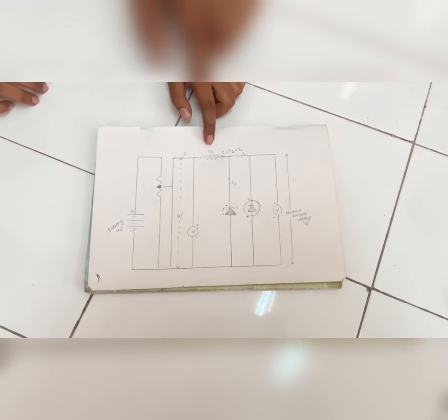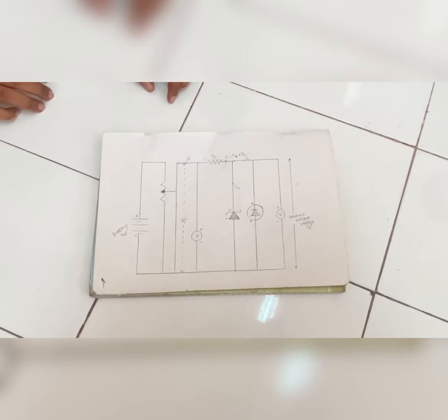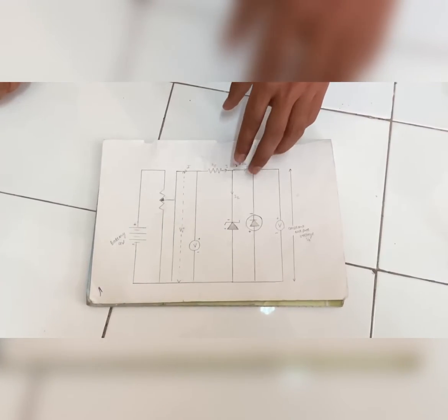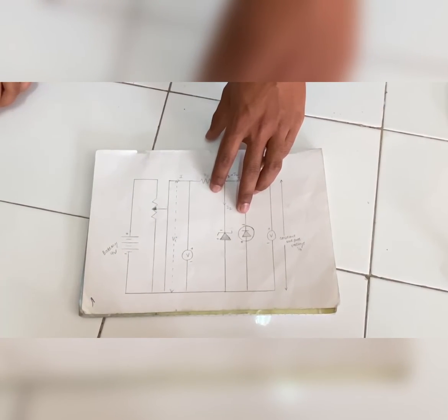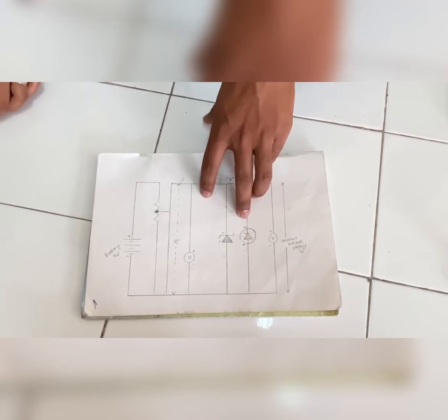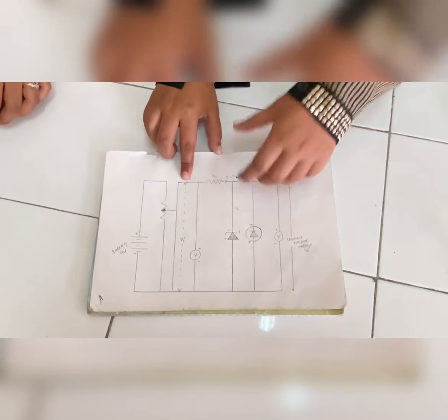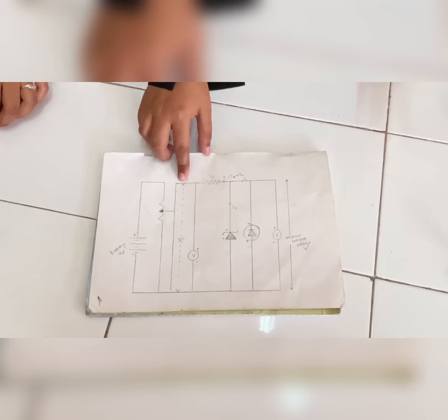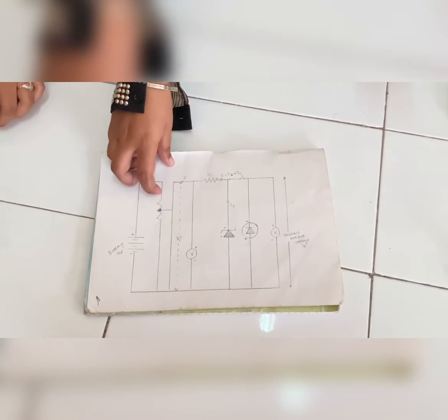And in the series, we have connected the resistance Rs and a Zener diode having a breakdown voltage Vz. We have connected load resistance in parallel with the Zener diode across constant output voltage. Here we use a series resistance because it prevents the Zener diode from being damaged due to excessive power dissipation. And here we use a potentiometer over any other device because it acts as a volume knob.